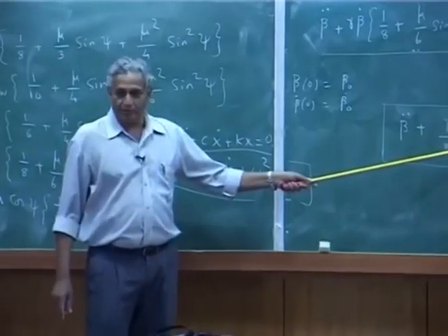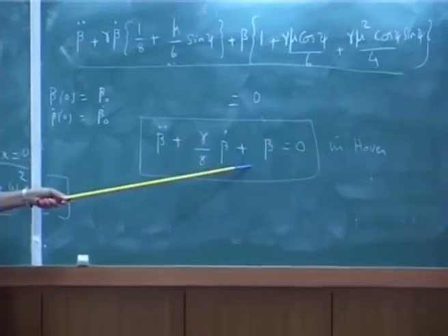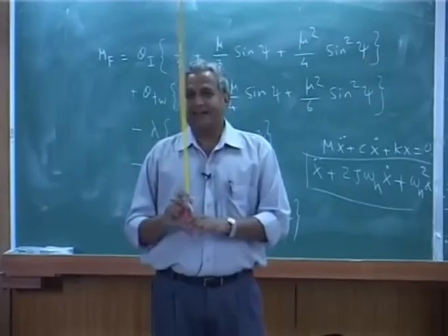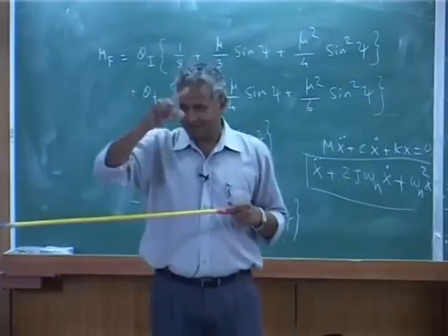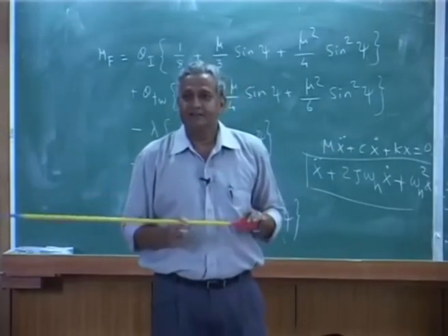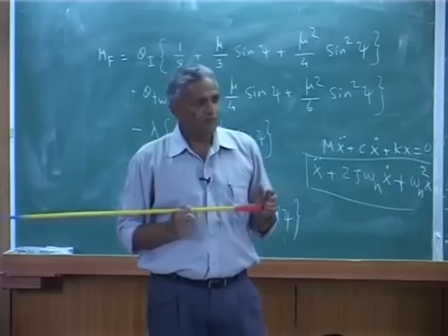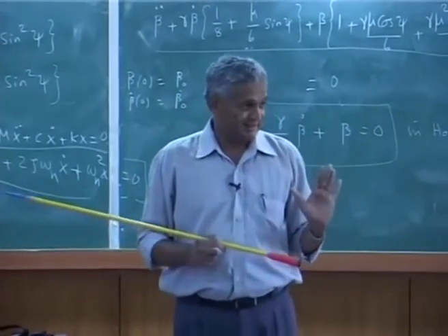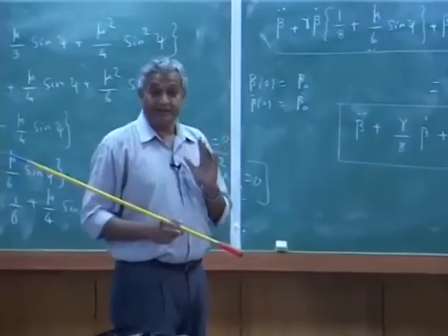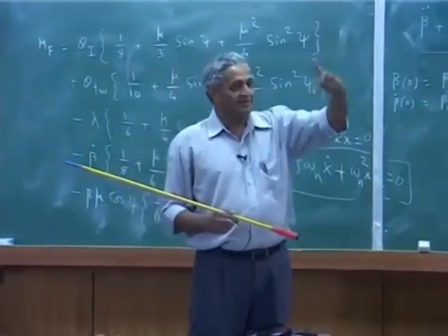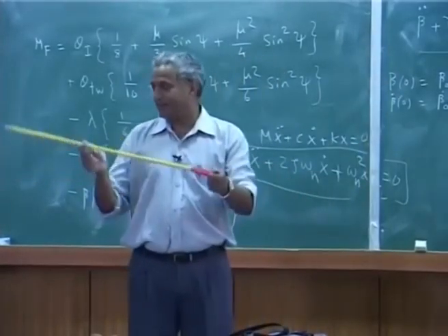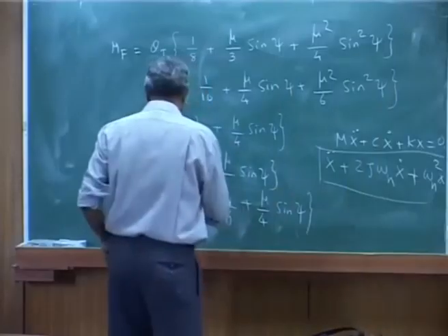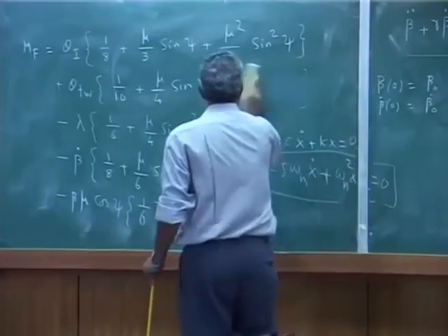Here the natural frequency is 1. 1 means here it is a non-dimensional. Okay. So when the blade, if it is rotating, if you tap it, it will oscillate. The time for it to go up and down, one oscillation is exactly equal to the revolution time. Okay. So the rotor RPM is actually the flap frequency. Only in this case, please understand. That is why we call it 1 per rev. 1 per rev. 1 oscillation per revolution. Okay, that means if you tap it up, it will go down and then up, down. Then when it comes to 1 oscillation, blade would have gone through 1 revolution. Okay.